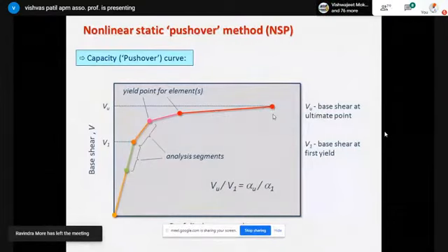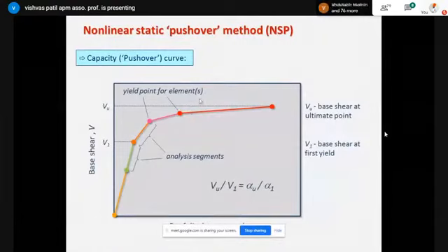From the point where it is yielding, what is important is the inelastic displacement, and we get that information from this. Inelastic deformation is nothing but, after yielding, from this point to this point, whatever this deformation is, this displacement is called inelastic displacement. What is the significance, what is the use of this inelastic displacement? Inelastic displacements are the displacements which are there after yielding. The structure in which inelastic displacements are more, we call that structure more ductile.